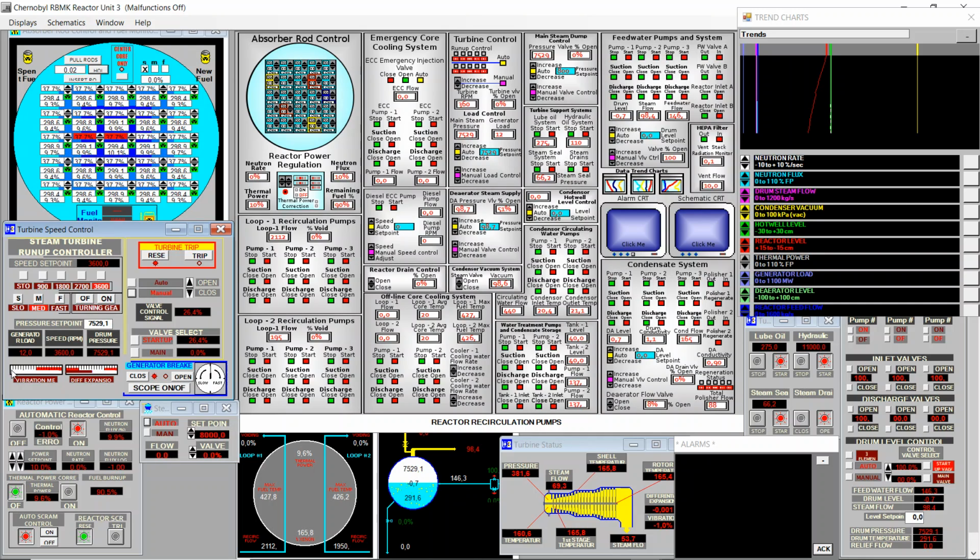If we just go offline and the load is the same, it means the valve is open at 26%. The turbine will spin up to like 3,800 RPMs, and it will break down because we will not be able to close the valve on time. So now I will manually reduce the valve opening until we get a generated load close to 0. It means we have very little excess power to spin up the turbine once we go off grid.